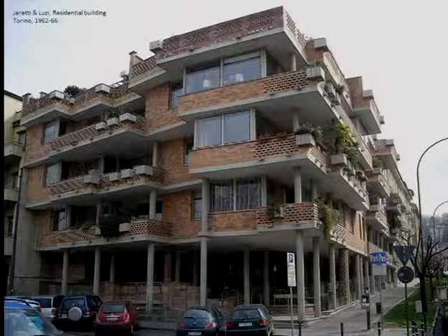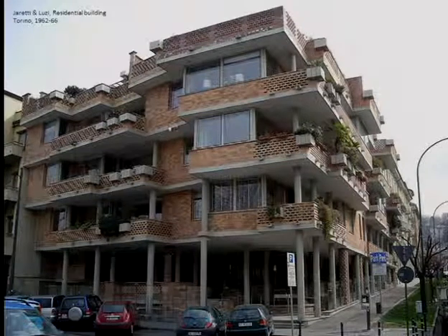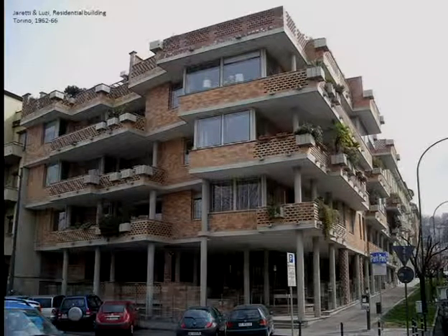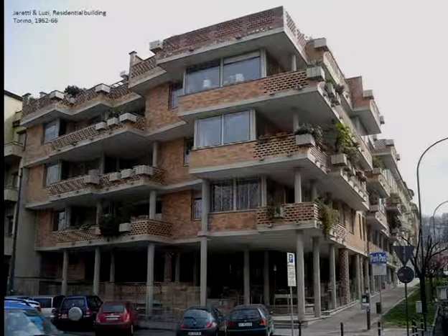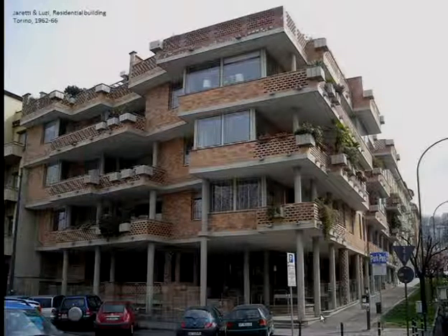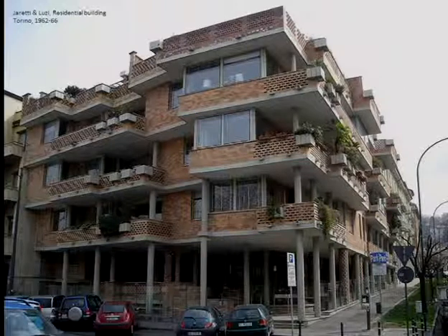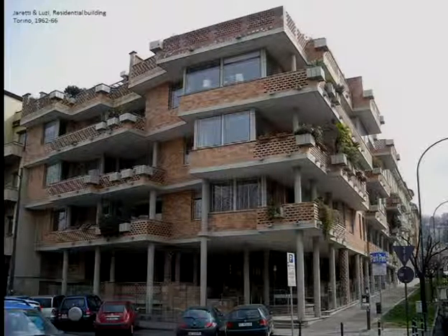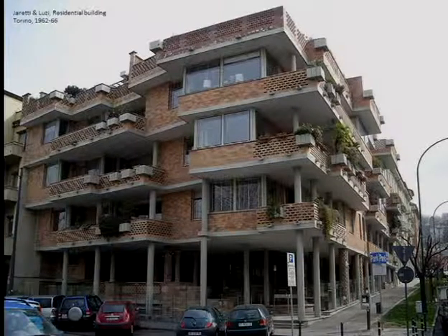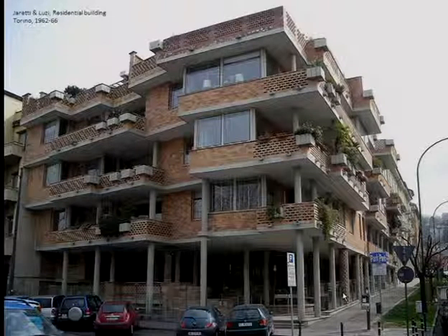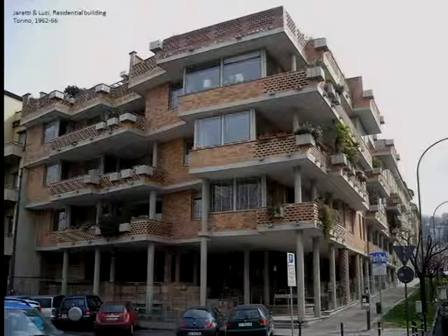So this is one thing. You also see that all the concrete frame is visible in the facade, so you've got a few thermal bridges. And in order to save material, what they also did, they only bought one single formwork to make the columns, because it was very difficult in that period to find circular formworks. So they bought one, it was very expensive, and when they needed more structural capabilities, like in this case, they just doubled up the column. So they put two columns beside, but just one single formwork.